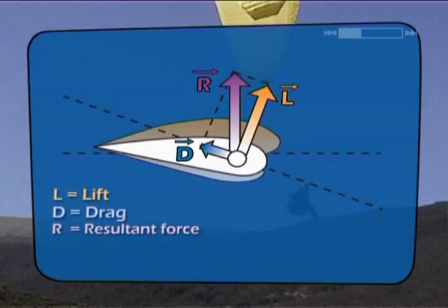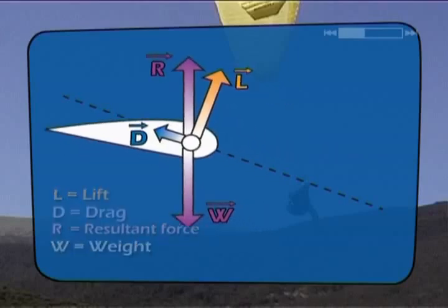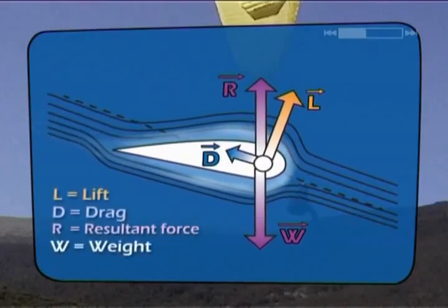How do we obtain the relative airflow necessary to create lift when there isn't any wind? By simply transferring his weight to the wing, the pilot pulls it towards the ground, forcing it to move forward through the air. This movement we call airspeed, and this creates the relative airflow required to produce lift. Altitude, therefore, is the paraglider's energy reserve, and by using our weight to draw on this reserve, we're able to fly.